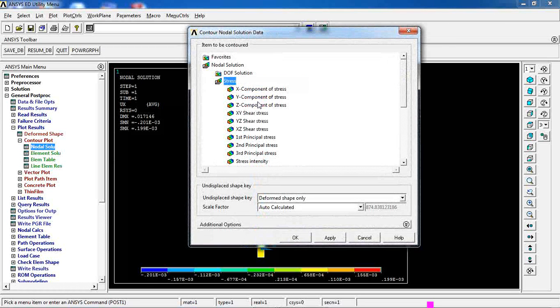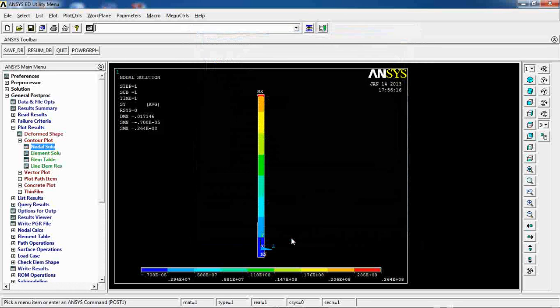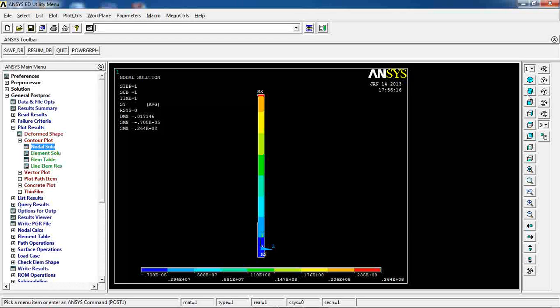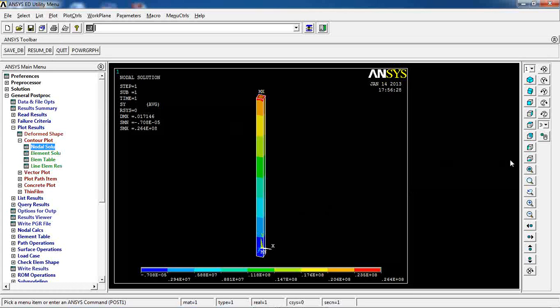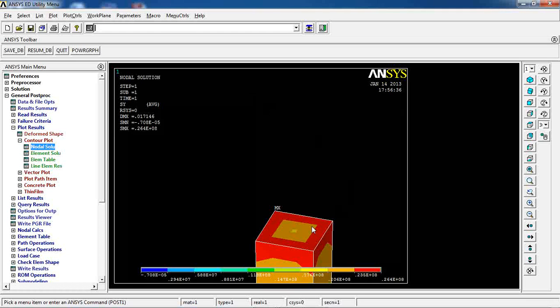And then let's see stresses in Y direction. Again, it's somehow similar to what we saw yesterday, except for today because of my meshing, it's not as precise as the model in lesson 7. But something you want to pay attention to is the fixed end. It's not a constant stress in here. As you see in the middle, there is a little bit difference compared to the edges of the sample.